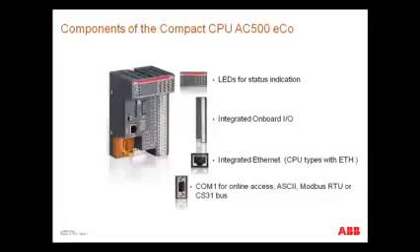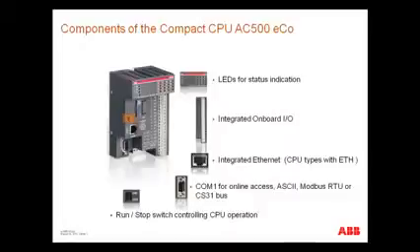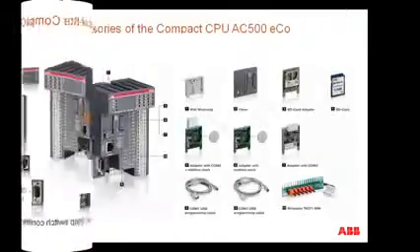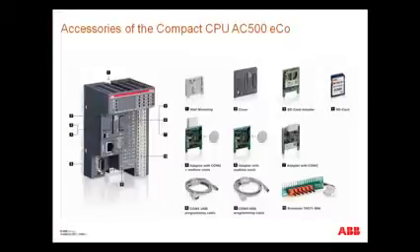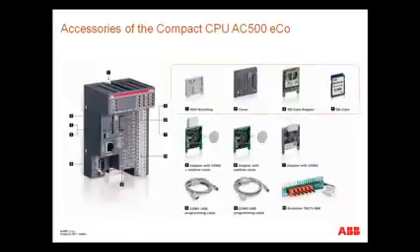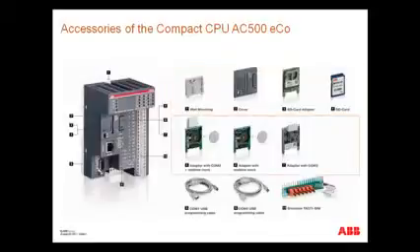COM1 is an RS485 serial interface. It can be used for online access and different serial connections. The program execution can be controlled by a switch. With regard to your needs, you can equip the controller with the following optional accessories: wall mounting and cover plates, or SD card accessories, additional COM interface, or real-time clock option, programming cable for COM interfaces, and signal simulator.